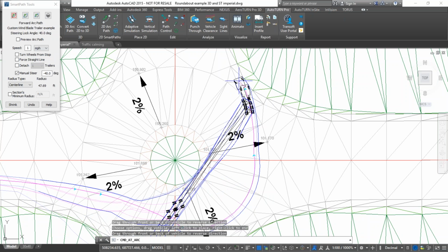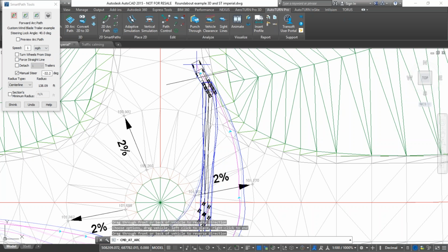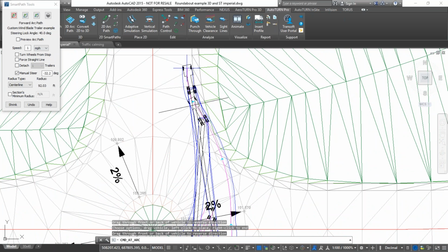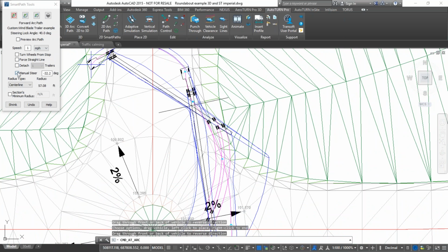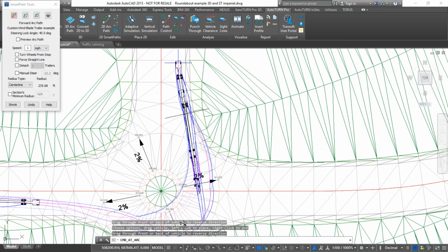So we can go over there and then keep driving. Maybe we can start straightening the vehicle a little bit. Now we have passed the obstacle, and from this point the vehicle is ready to keep going, we can switch back again to AutoSteer, and then the wheels will follow the trailer with the proportion indicated on the steering linkages.